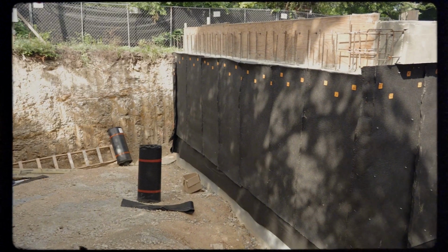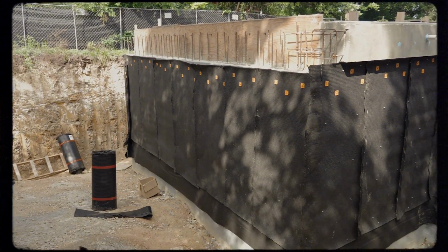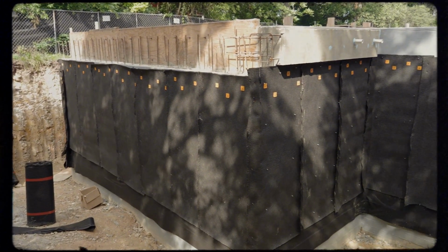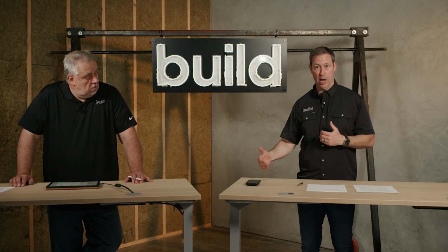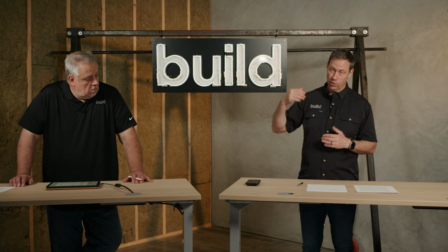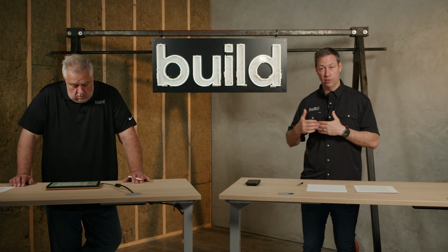But that drain board or protection board, whatever you want to call it, makes sure that the waterproofing isn't challenged because of what Steve mentioned earlier, backfill issues, or even really heavy rains that allow that water to kind of rise up. It gives an air gap in front of that waterproofing and in front of that concrete foundation. So any water that's flowing towards the foundation is going to hit that air gap and go all the way down to that footing drain where it can be pumped out.